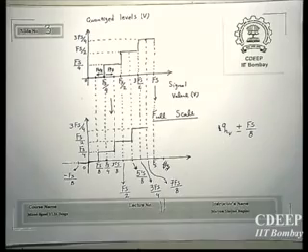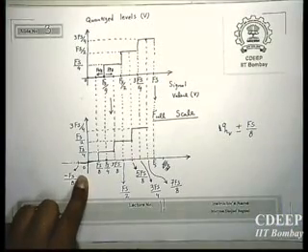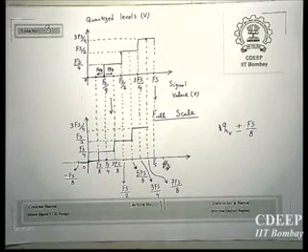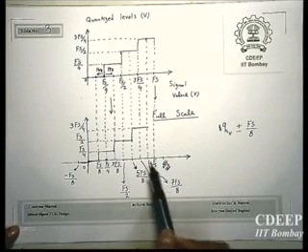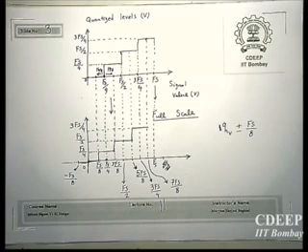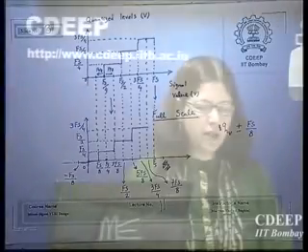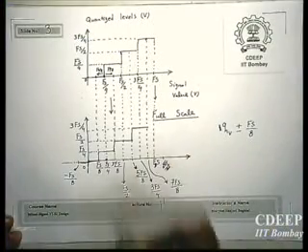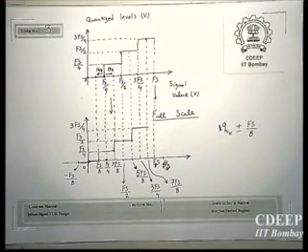See exactly why this is happening: because at the 0 side I have lost this. Here I have one more interval, or more headroom for positive noise, only at the last level. But usually we don't go to the exact full scale. We always prefer the signal to be below full scale, because in the vicinity of full scale we have a lot of problems with the comparator. A comparator cannot have a resolution of 0 volt. Therefore, it's better to always be below full scale.